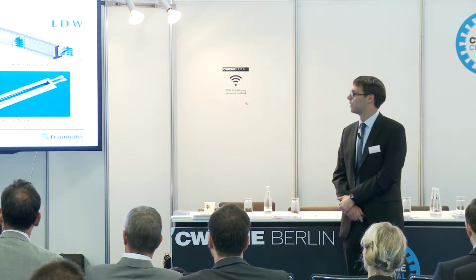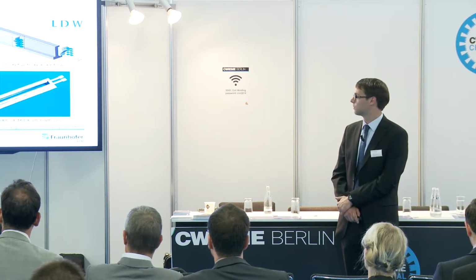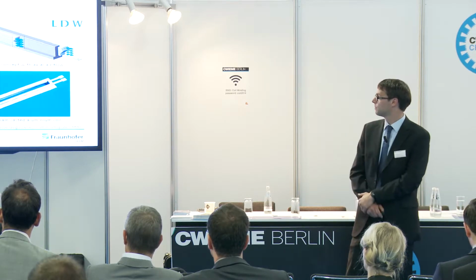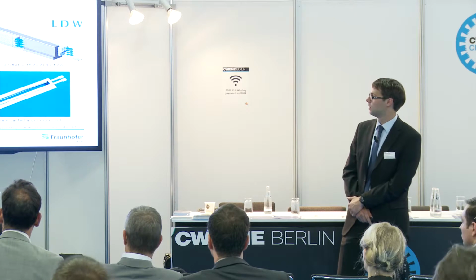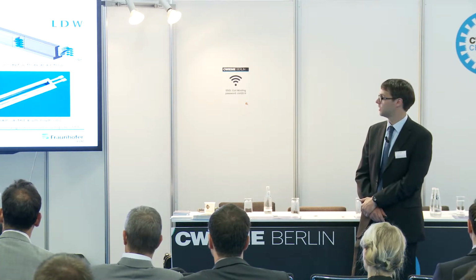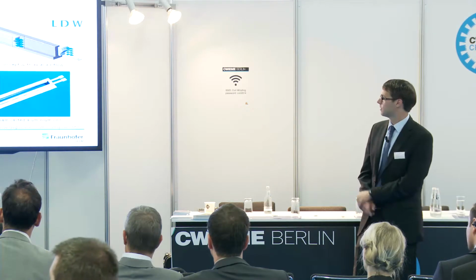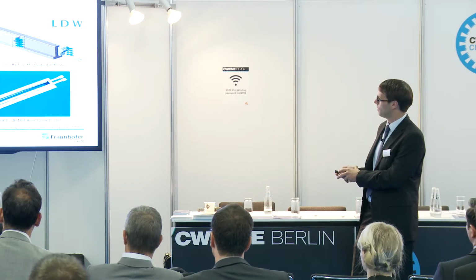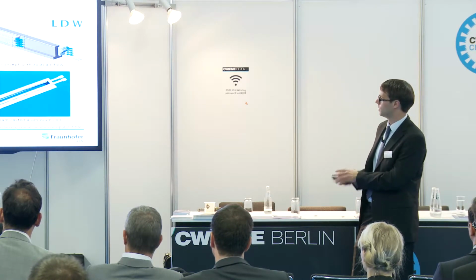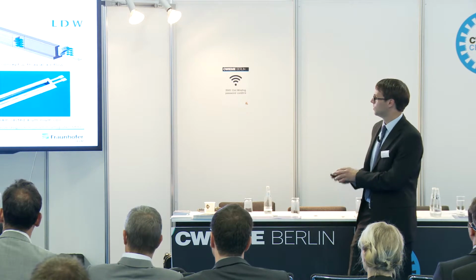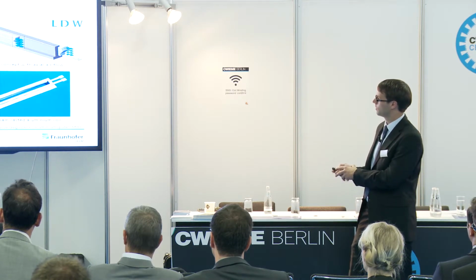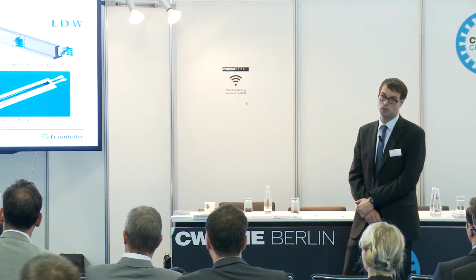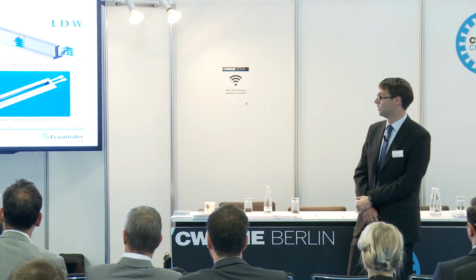The first industrial application of the process was realized in collaboration with the Bremer Lloyd Dynamo Werke. We realized a coil, a commutating winding of a 470 kilowatt DC machine. And in this concept, we realized an innovative cooling concept. We used the geometrical flexibility of the coil to realize axial cooling concepts. So we had an air-cooled machine and we were able to replace a wound copper coil with an electrically equivalent aluminum coil.